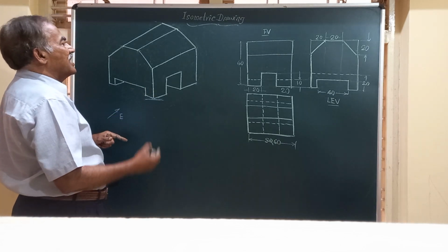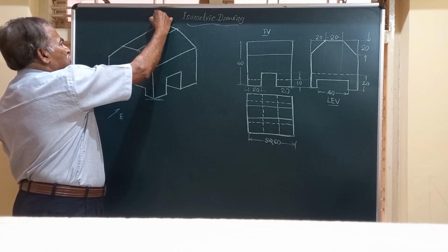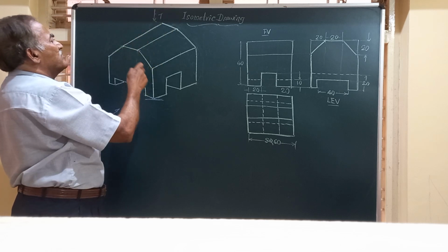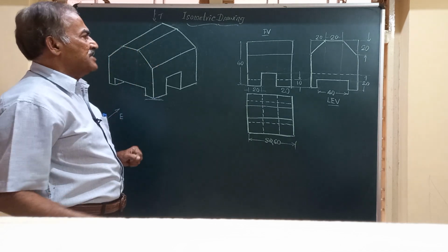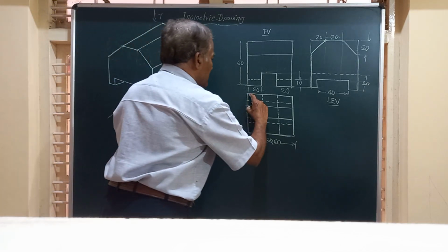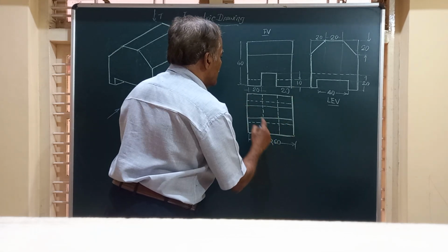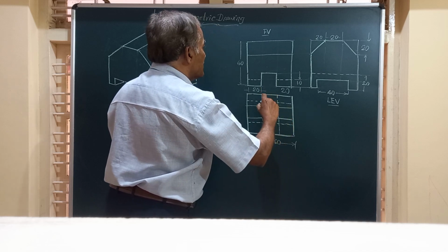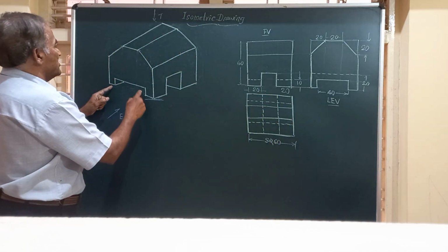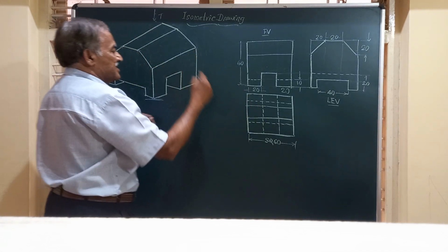20. And in the top view, friends, if you look from the top, from this direction, you will be able to see 1, 2, 3, three rectangular surfaces. One, this is the second, this is the third. These two dotted lines indicate the slot as a rectangular slot in the top view, which are parallel to these edges.